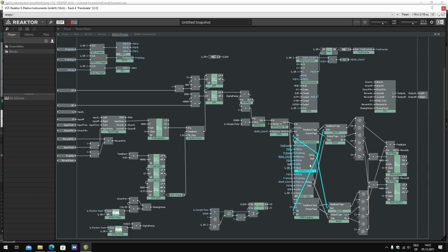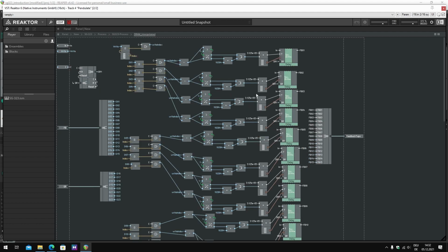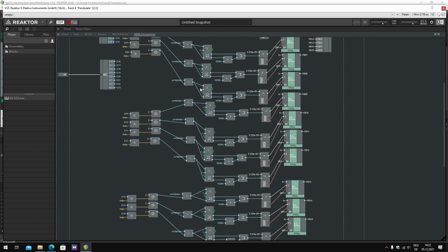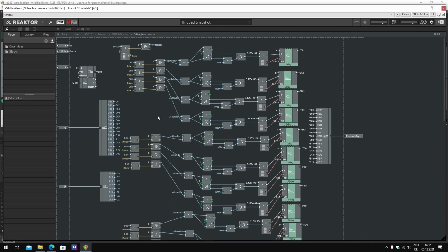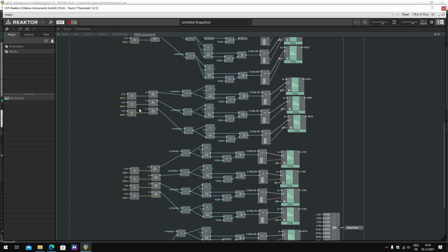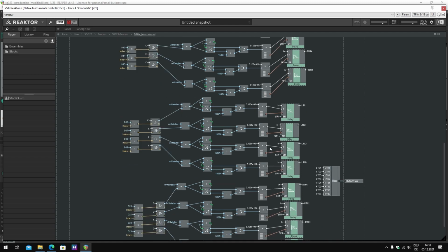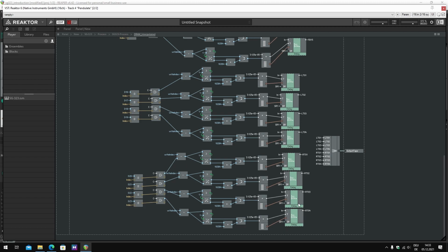So the delay times. If you look in here, it's lots of the same stuff, because internally the Stargate 323 has 23 delay lines, like 23 single separate delay taps. 15 of those, the first 15 in here, up until this point, are used for the feedback signal, the next 4 are used for the left output signal, and the last 4 will be used for the right output signal.